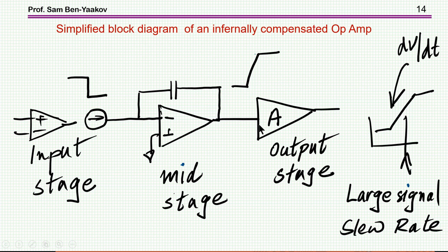And then there is an amplifier, so actually it's amplifying, so in fact you get here a gain and therefore the rate here is faster. So very typically an operational amplifier, when you have a step input, that is, there is a need for a change, for a fast change, it will swing at a given rate, which is called the slew rate, and this is kind of limited because of this exact capacitor we are talking about.